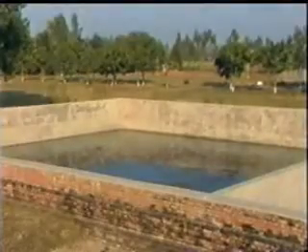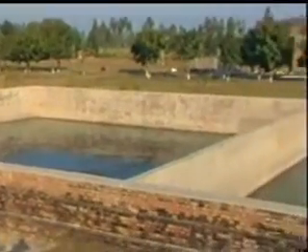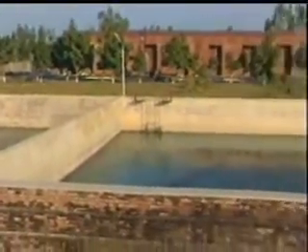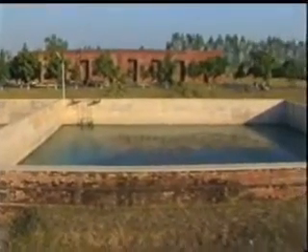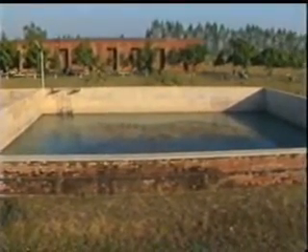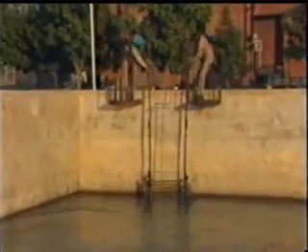This water is carried through pipes or open channels to the suction tank. At the suction tank, larger size suspended matter is retained on the screens provided at the outlet, thus allowing only the screened water to reach the pump house.